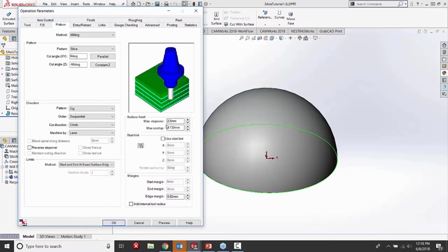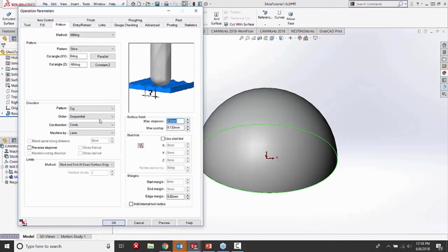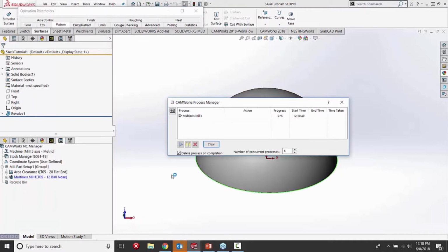And a lot of times with these toolpaths, they take so long to generate that I really recommend turning down your cut amount. We want to keep the toolpath a little bit spaced out. The tighter we make our step over here, the longer it takes to generate, and we're still really just in the initial phases of this. Let's keep our step over broad, just get a general idea of what the toolpath looks like, and narrow that in. Once we get it looking good, that's when we can finally come in and really tighten up our toolpaths and let the machine sit for a while and take a couple minutes to generate this really complicated toolpath. So before we go much further, let's take a look at the toolpath.